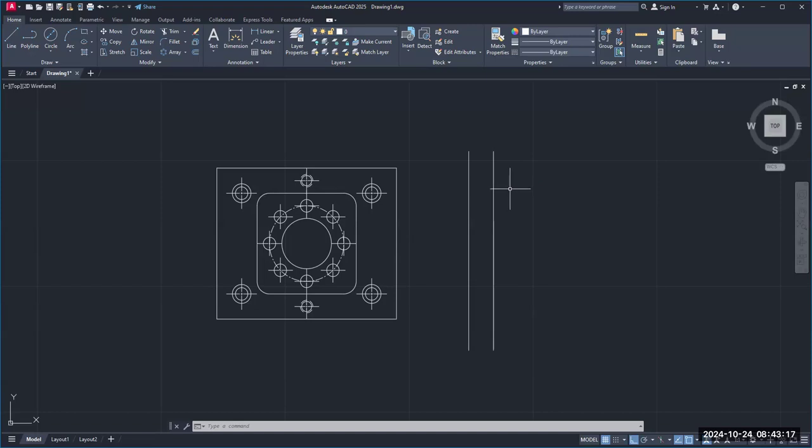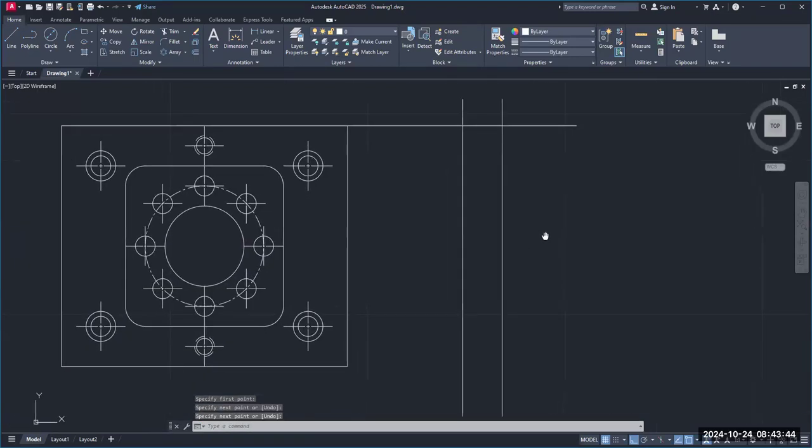All right. Now, what I want to do now is start doing some projections. What are projections? Well, I'll demonstrate the first one. Everywhere there's an intersection over here, we want to draw a line from that intersection and project over to the right. Here's how this is done. Go to line, click on this intersection right here, click, and project over. Don't worry about how long it is. Click, enter. All right, very good.